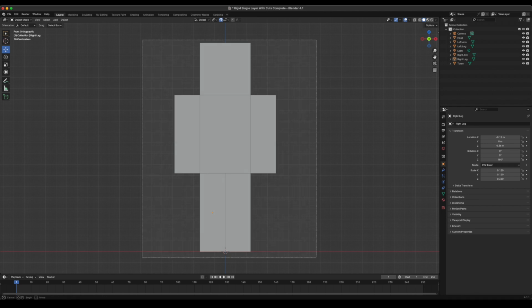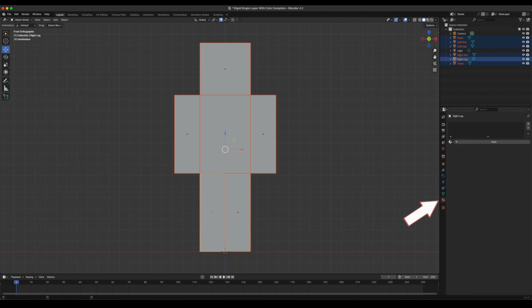The first step we need to do is to select our model in object mode. With the model selected, we will now go into the Material tab of the Properties editor. This is the tab represented by the quartered circle that looks a little like a beach ball. It is also the same icon as one we can choose to show how the model appears in the viewport. We will click New to add a new material to our selected objects.